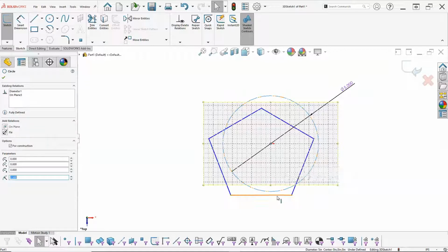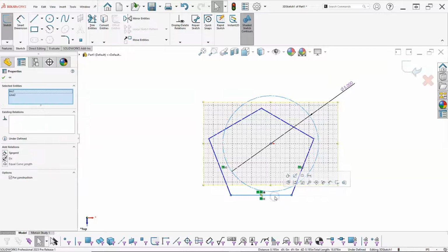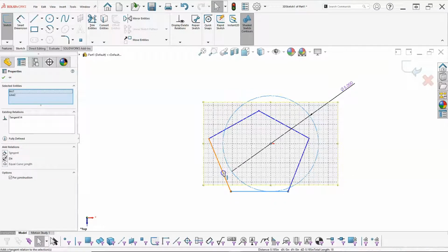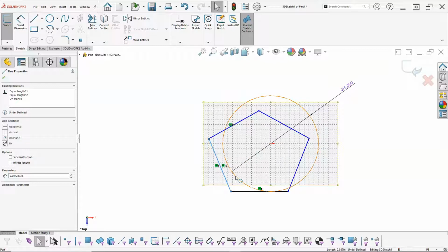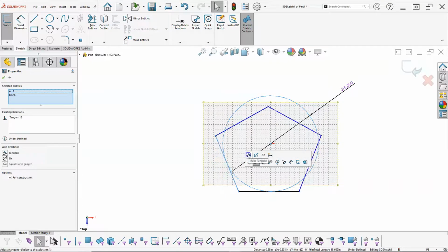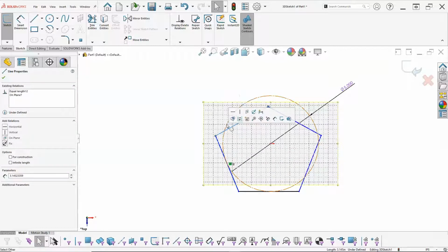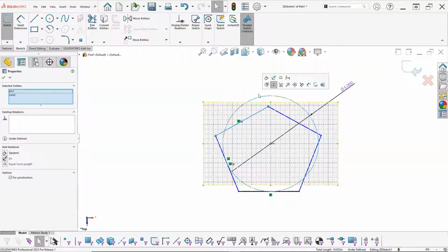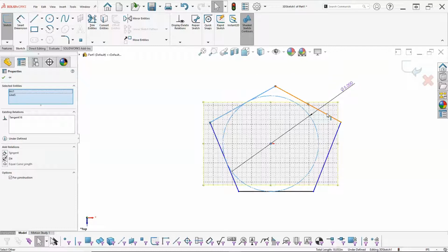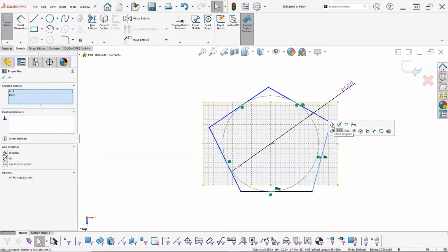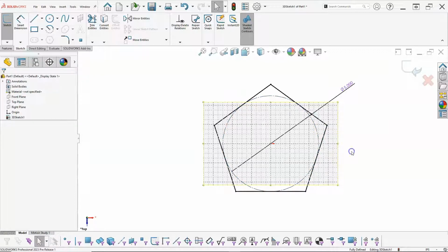So the selection process is to select, Control select, go to tangent, pick something that isn't selected so it clears the other 2, hold down the Control button, tangent, select, clear, and it's doing the clear automatically. So all I'm having to do is select something that's blue, and it clears the selected items. Right, so in this case, the darker blue. Oh, and this doesn't have my magenta for the first selection, so that's why they're showing up in the cyan or the light blue. So a little bit different maybe from the other videos.